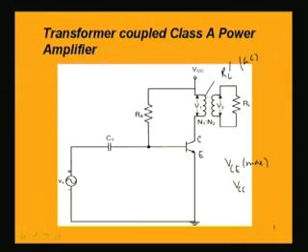So, if the flux goes down, then due to Lenz's law, there will be an EMF opposing the very cause behind it. That means it will not let the collector current collapse, and to overcome that, it will be aiding the voltage by increasing it to 2 times VCC.